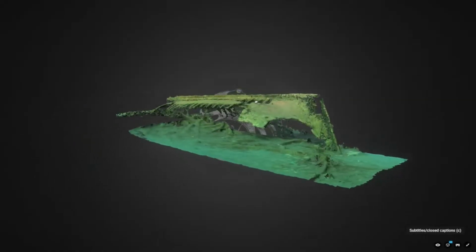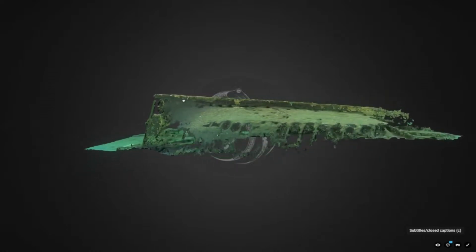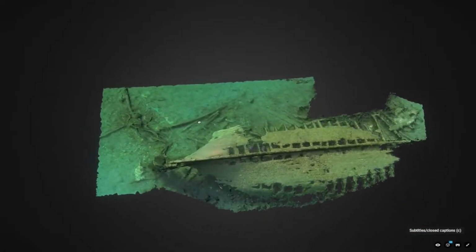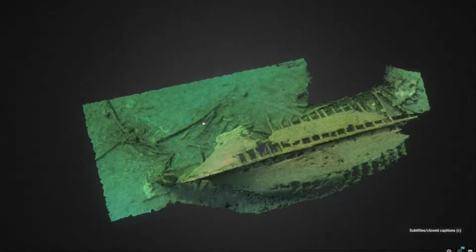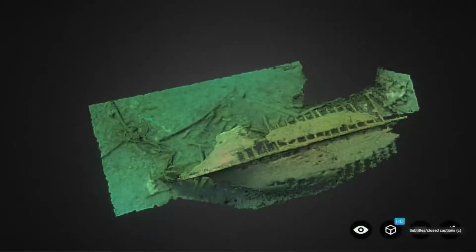So this is actually a boat that sunk, and you can see all the different ribs that are here. And this is from one of those ROVs, basically doing a lawnmower pattern with the camera facing down. It's a GoPro, and it just goes back and forth, takes all those images, and they're able to create this 3D model from all those images. It's really cool because you can get a good perspective, and depending upon the quality of your camera, you can get really high detail in these models.